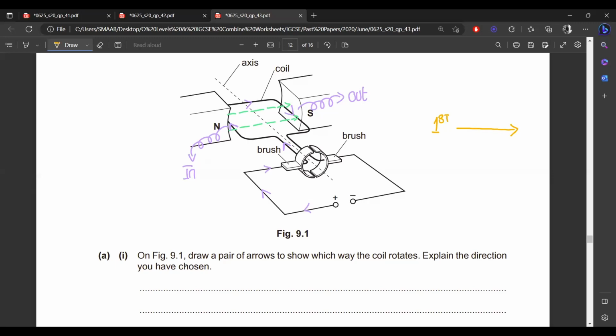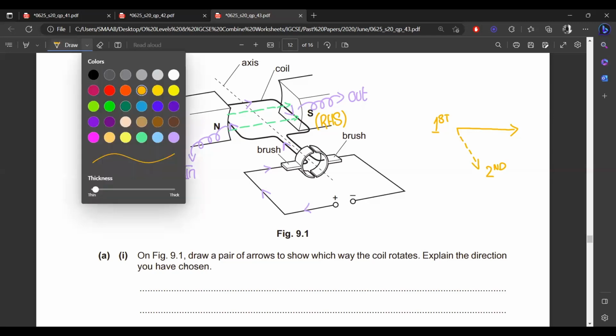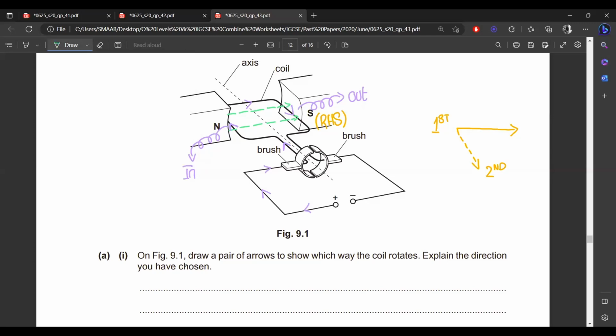So now when you open your second finger, it is pointing towards you, right? Yes. When the finger is pointing towards us, it means we are talking about the right hand side, because current is moving out of the page from the right hand side. So first we are finding the direction on the right hand side. The finger is pointing towards us on the Z axis, let's say. And now open up the thumb. Which direction are you getting from the thumb? Upward direction. So it means that force will act in the upward direction on the right hand side. This is the direction of force.